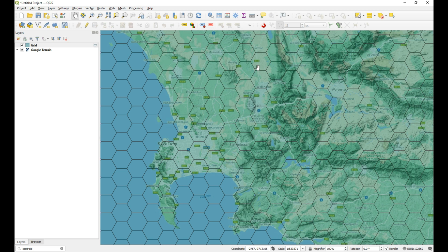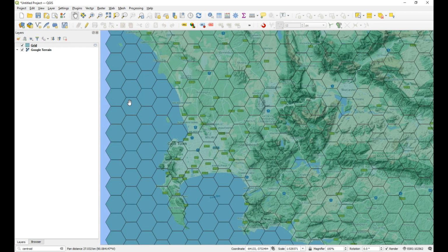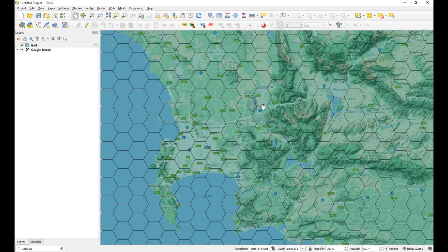Okay, so in this projection, by choosing Hartebeesthoek94 LO19, the least amount of distortion will happen for your layers. So your measurements, perimeters, areas, and calculations for that sort of thing are going to have the least amount of distortion here. The further east and west you move away from your center point, the greater the distortion will become. Okay, so that is something to bear in mind. If you are working in an area, make sure you choose the projection with a meridian closest to the center of your study area.